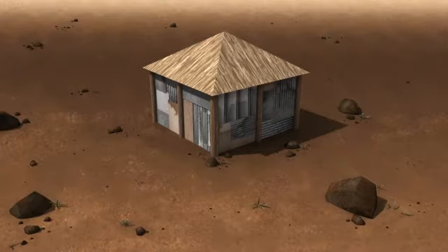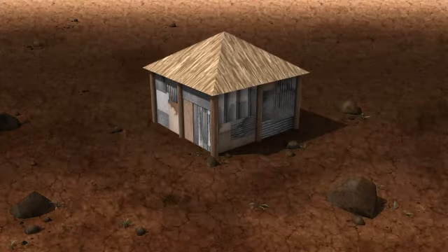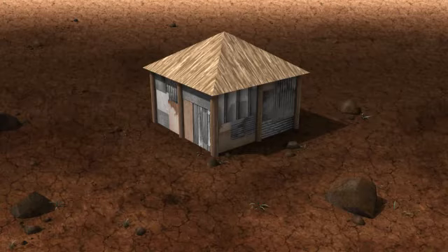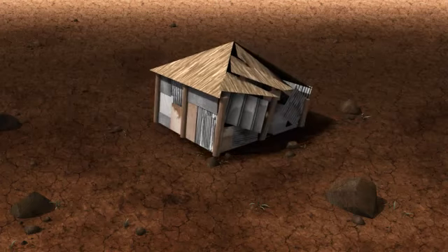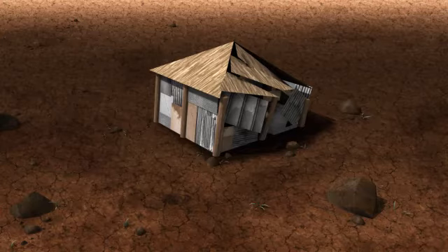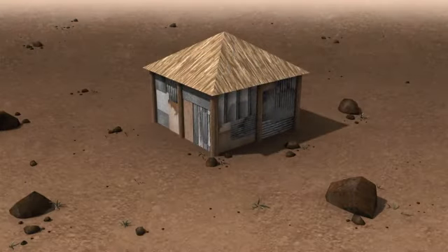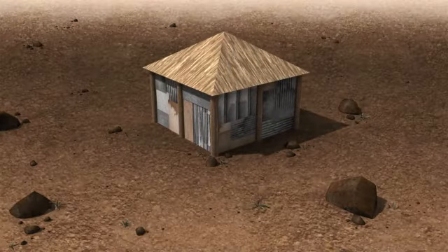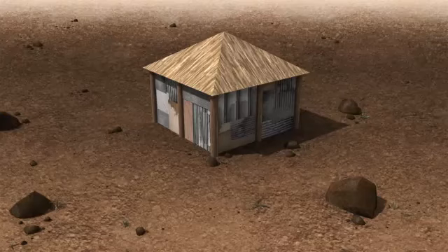Neither sand soil nor clay soil is suitable for construction of the shelter, as they are too soft and thereby unstable for the foundation. The shelter may crack, collapse or sink into the soil. If no alternative is available to sand and clay soil, a deep and wide foundation should be built to at least minimize the risks. However, recommended is a harder type of soil found on more rocky terrain. This provides a more stable base for the foundation of the shelter.